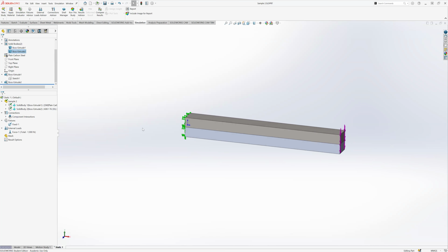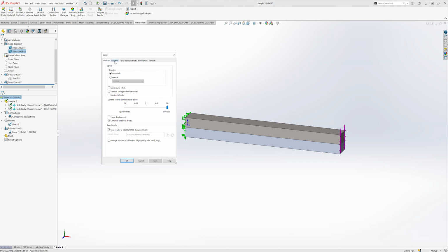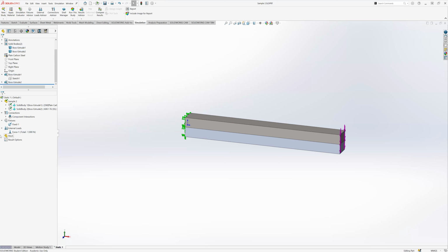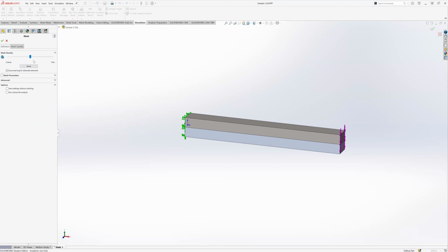So what we'll do here is go to mesh. I'm going to check here real quick. I don't think I have any adaptive on, and I don't really need adaptive. Yeah, we'll just do none. Okay, so let's go to mesh, create mesh. I'll do something intermediate, maybe bump it up a little bit. Blended curvature is probably fine.